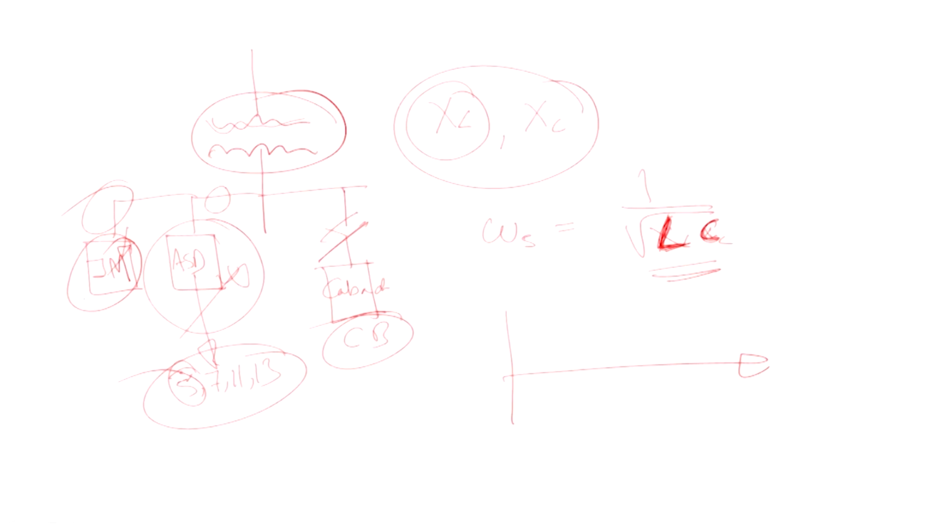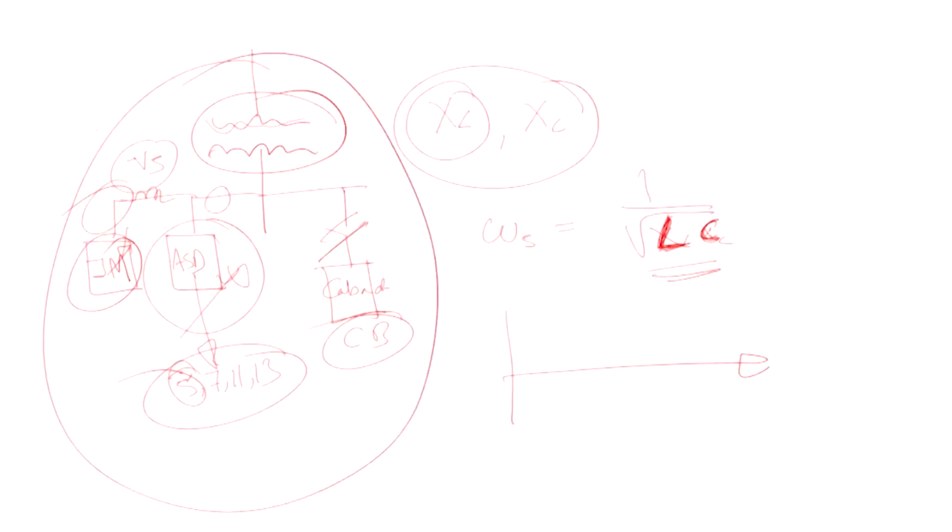Because of the source inductance of this wire, the 5th harmonic voltage will also be generated, and that will go into the machine, and ultimately it will produce a ripple torque, a torque negative to the fundamental movement, and thus cogging will take place.